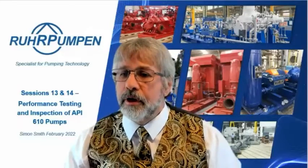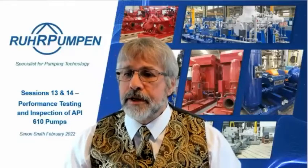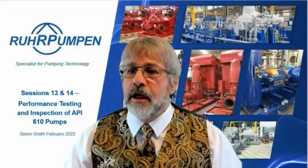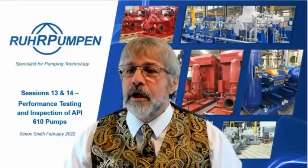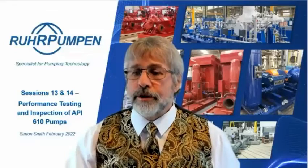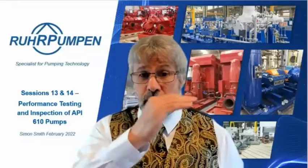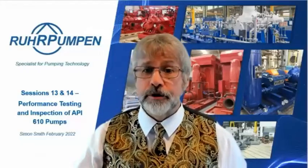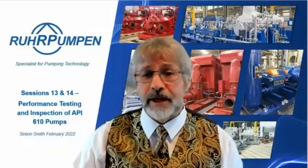Okay, here we go. One here. How is the seal flush piping tested? We got that in the Q&A as well. Are you carrying out NPSH test at rated point or covering all the points? The NPSH test is at all the points, so from minimum continuous flow to run out. You carry it out at all those flows, typically 6 points.